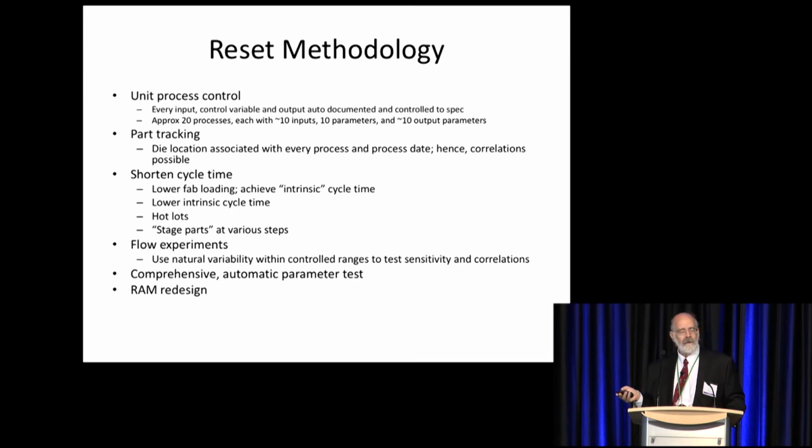So we reset our entire methodology for testing and diagnosing these circuits. And I'm going to go in detail on some of these things, but I'll just go briefly through it. We instituted a unit process control, which means every sub-element of this process, inputs, outputs, and intermediaries, are monitored and tested. We tracked every part, so when a part goes through a process step, we know exactly all the parameters that part has seen. We shortened the cycle time of the process.